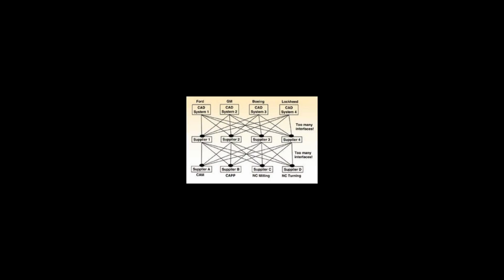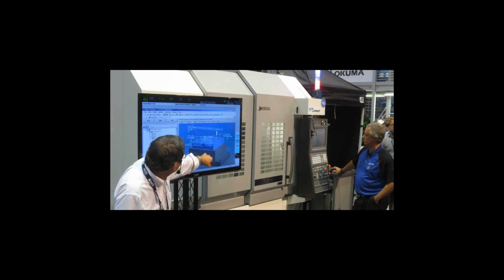STEP GD&T information can also be added to enable quality measurement on the control, and CAM-independent volume removal features may be added to facilitate regeneration and modification of the toolpaths before or during machining for closed-loop manufacturing.